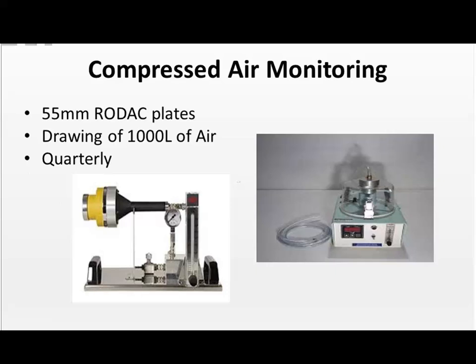It can draw in as much as 1,000 liters of air, and this is a 55 millimeter plate, and you're going to then incubate that plate at 35 degrees C and see what type of bioburden you're getting. Typically, our compressed air is monitored quarterly, and also if you have nitrogen ports, you're going to do the same. You're going to monitor those quarterly for bioburden in the same manner.